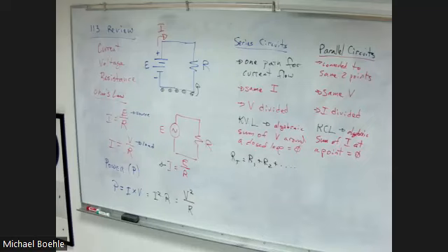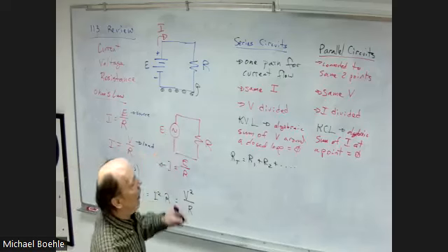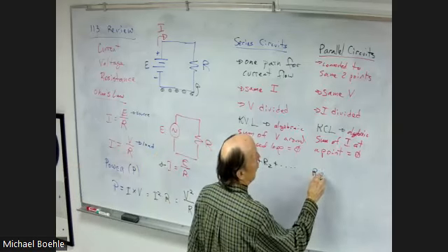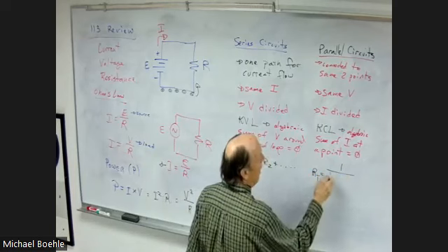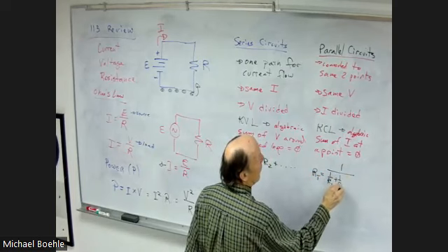So we're going to get a review of Kirchhoff today. It's going to be a big part of what we do. Everything I just reviewed, Ohm's law, Kirchhoff's current law, Kirchhoff's voltage law, that's all we're going to use today for that advanced circuit analysis. Literally, that is it, as far as laws and rules go. Now, if I have resistors in parallel, their total resistance is the inverse of the sum of the inverses.